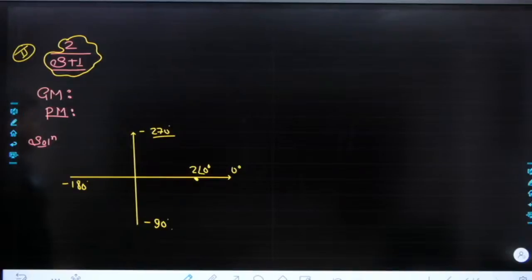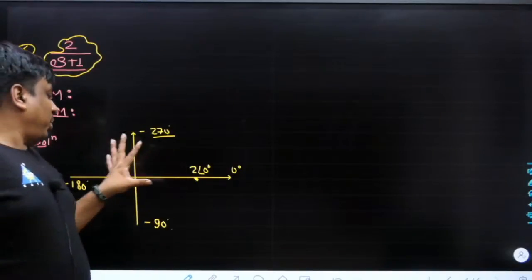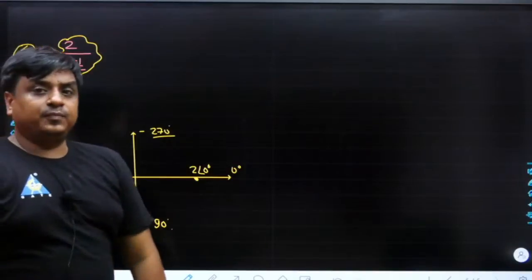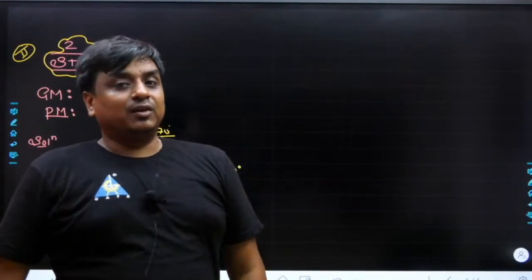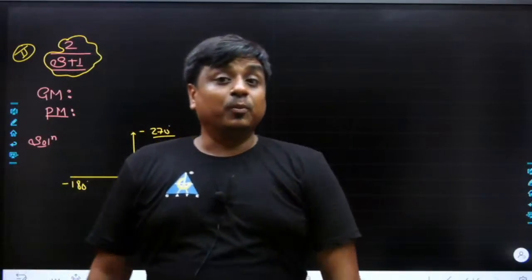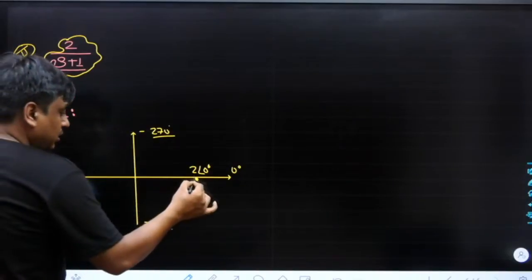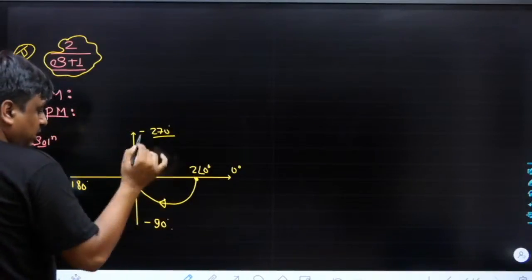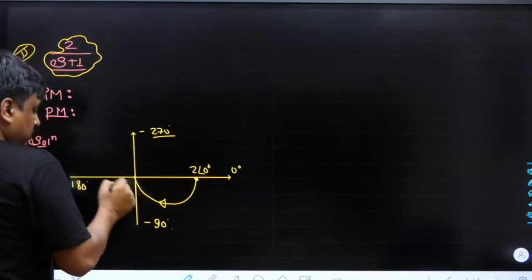As the value of omega increases, definitely the denominator is going to be more and more heavy, so the magnitude would decrease. As the magnitude is decreasing, this point would start coming nearer to the origin, that is the first thing. At the same time, the angle offered by s plus 1 would be tan inverse of omega. As the value of omega increases, definitely the phase would be more and more lagging. And at the end of the day, the curve is sort of this. Agreed? This is 2, 0.